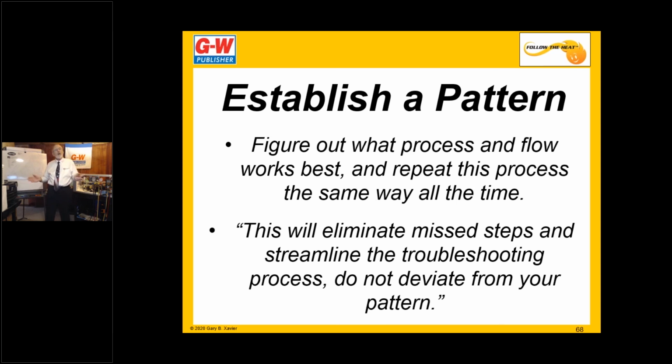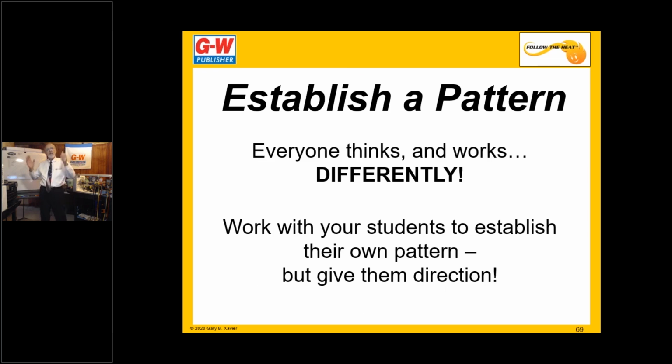It'll streamline your troubleshooting process, and you don't want to deviate from that. If I had started inside that day, if I had parked my truck and then ran indoors and said, hey, what's going on here? Look at the gauges, look at the thermometers. It would have taken me a lot longer to figure it out. So establish a pattern and stay with it. Everybody thinks differently, everybody works differently, but we can give direction. My pattern won't work for everybody else. Your pattern might not work for your students, so help them develop their own pattern. That's number 3.